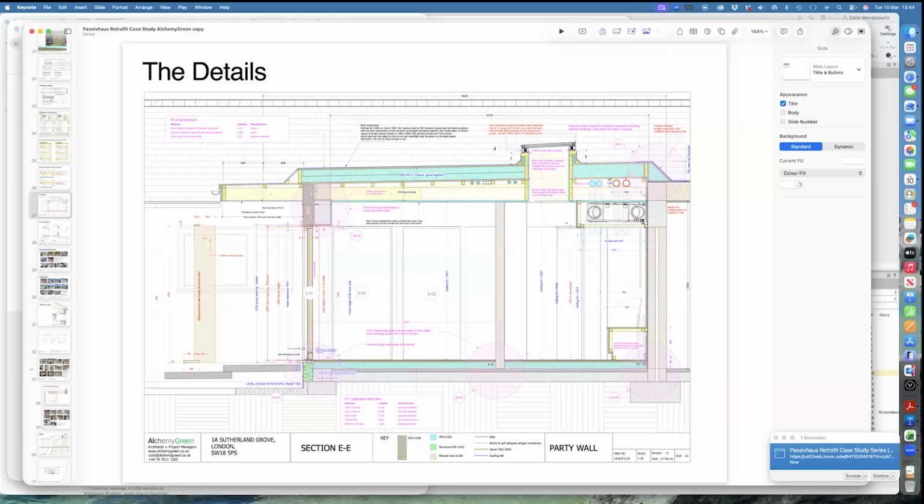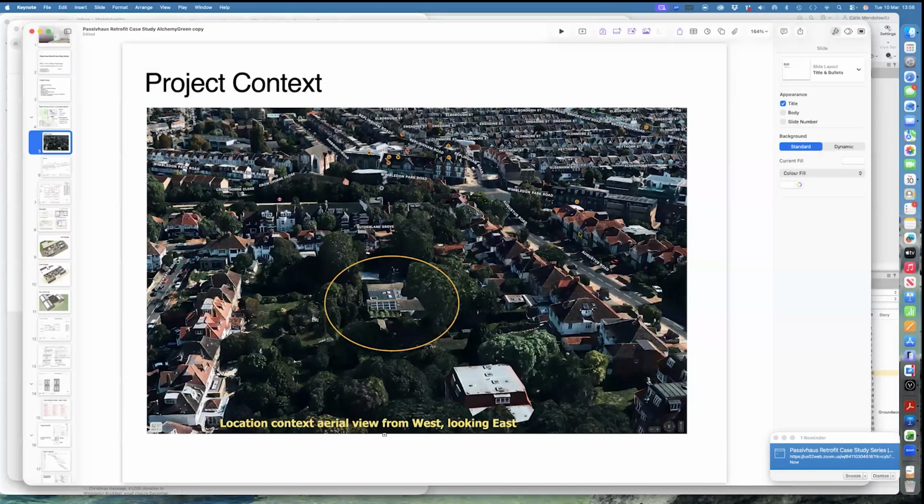You've got quite a bit of tree shading on the south elevation, which is the front door, out the side of the building. Colin put quite a bit of overhang in, extended out of the flat roof. I wanted a big overhang there, and that makes a big difference to the heat load on the front door and those two windows. It also means you don't get wet getting keys out in the evening when it's raining. You can see the context in this picture: it is surrounded by big trees.